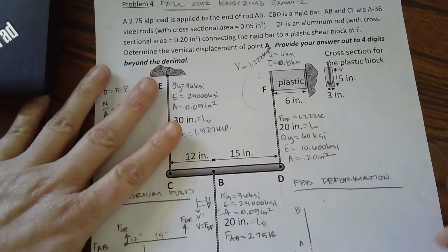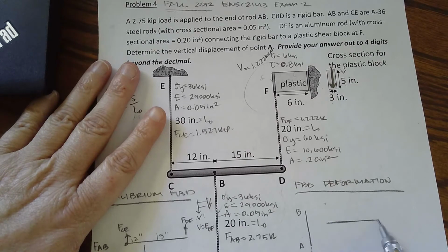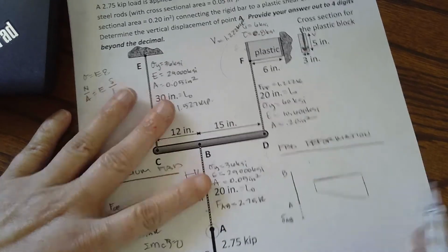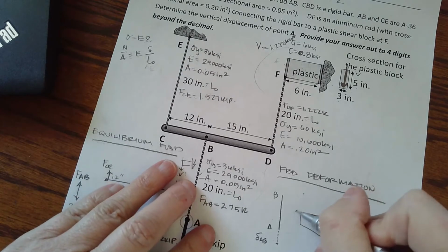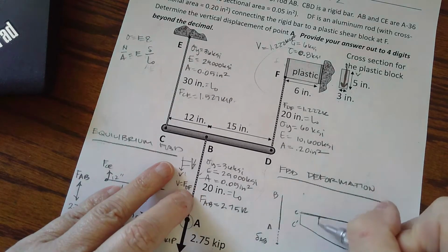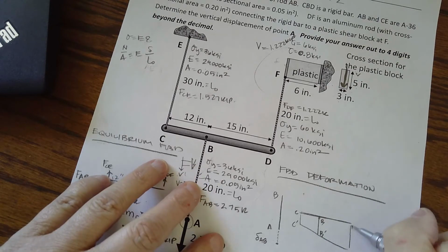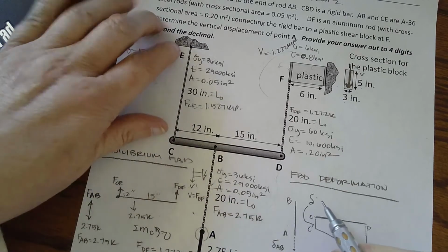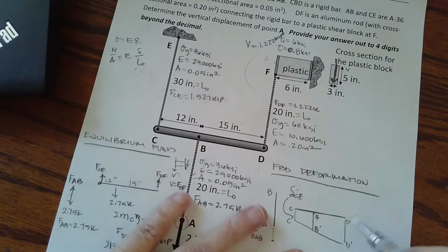Now I also have this rigid bar, and those cables above it are going to stretch, and I don't know how much, if it turns, if it twists, if it stays level as it comes down, I don't know, but I am going to go from C to C prime. Note that I have B to B prime and D to D prime, and I know that this has to just be the change in length from C to E. That's the only thing that's on this.